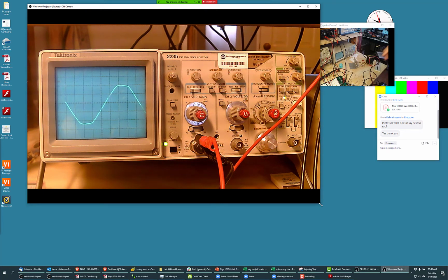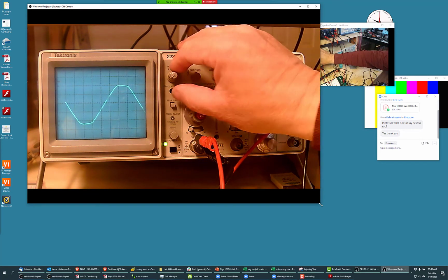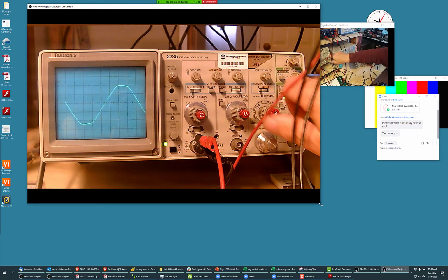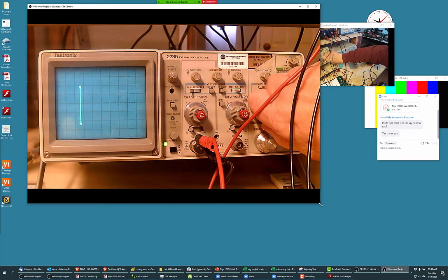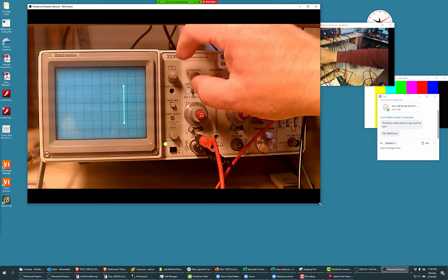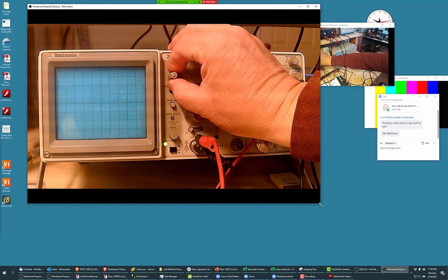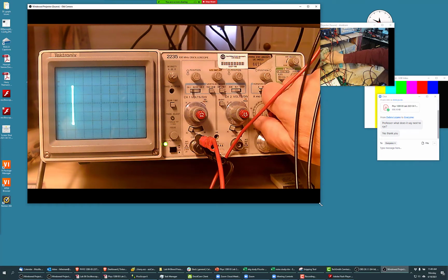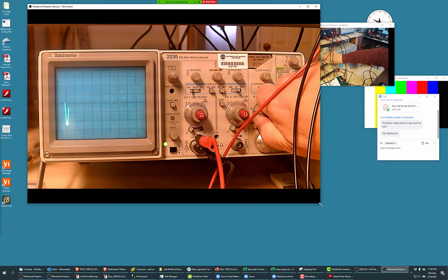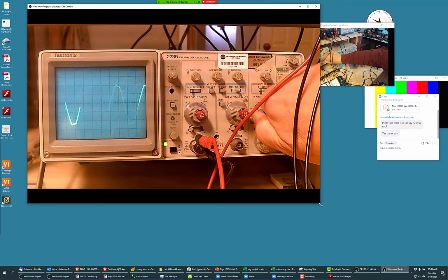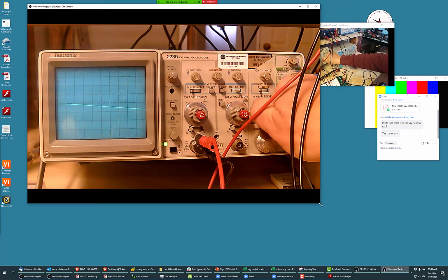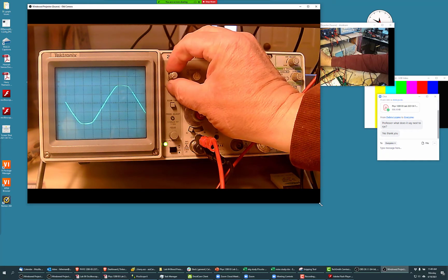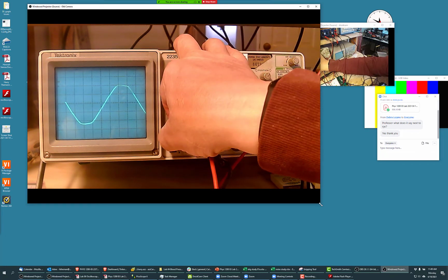So you have the beam quality here, where you can change the brightness. The slower it goes, the brighter it tends to get, so then you need to turn it down. And as it goes faster, it gets dimmer. It has to do with the dot hitting there, and how long a chemical called a phosphor glows inside. And then there's a focus knob.